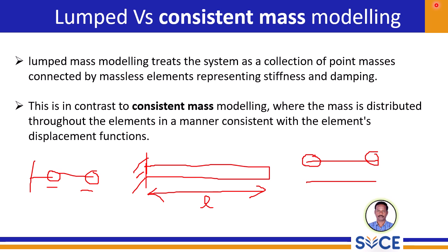In practical applications of Rayleigh's method, especially for estimating the fundamental natural frequency, a carefully chosen lumped mass model can provide sufficiently accurate results. However, for precise analysis or even investigating higher modes, the consistent mass matrix might be preferred. The choice often depends on the specific problem, desired accuracy, and the available computational resources.